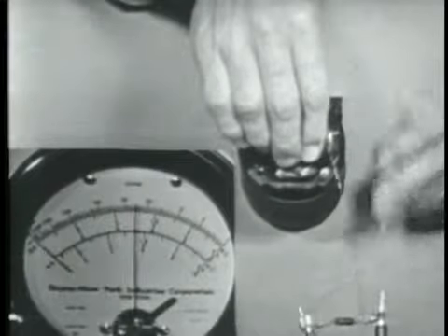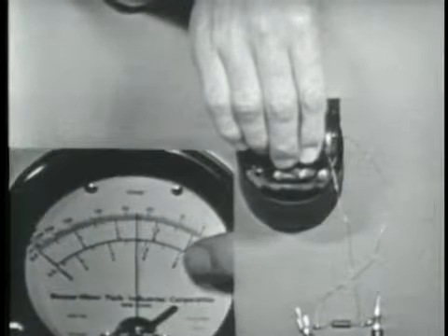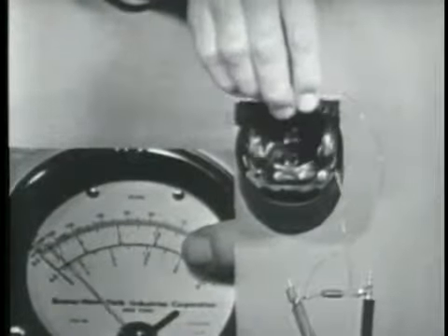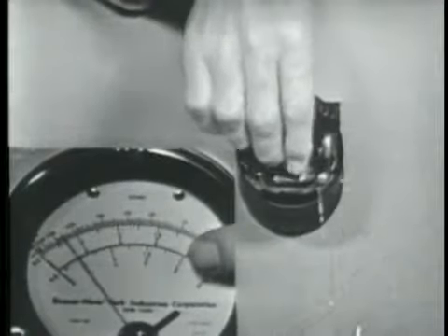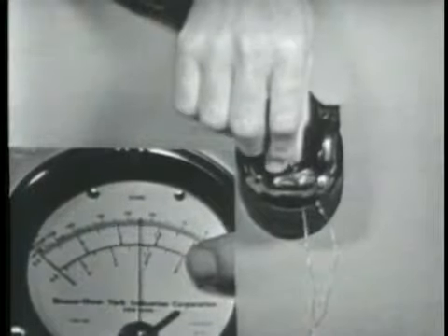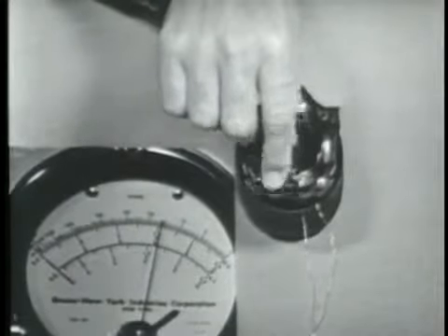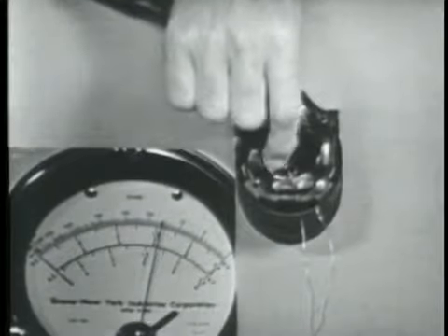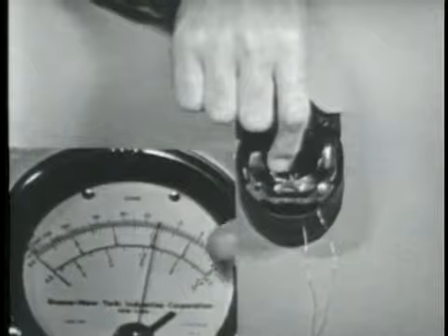That's induced voltage, huh? That's right. That's the induced voltage from this loop. And you can see that if I take the loop out, it goes away, put the loop back in. I've got to get the loop all the way down in there. There you go. Now we have the rotating magnetic field inducing a voltage into the loop, which we're reading on the PSM6.